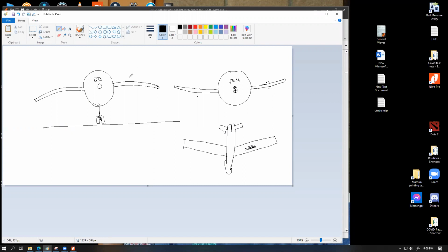Whenever on the ground, these things are going to be in an elongated state, then a flat wing, and the ones on the bottom are placed in different places actually. They are going to be in some sort of compressive state because the whole thing is curved downwards. Whenever the airplane is in the air, these top parts will be in some sort of compressive state because this is now curved inwards, and these bottom ones will become elongated.